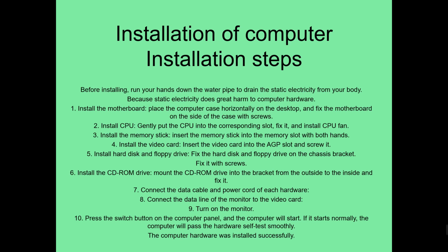2. Install the CPU. Gently put the CPU into the socket, fill it, and install the fan. 3. Install the memory stick. Insert the memory stick into the memory slot with both hands. 4. Install the video card. Insert the video card into the AGP slot and secure it. 5. Install the hard disk and floppy drive. Fix the hard disk and floppy drive on the chassis bracket.